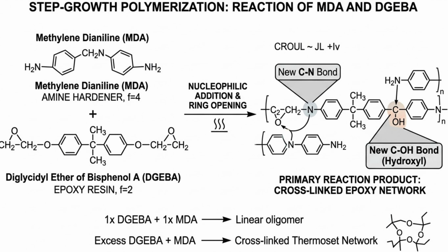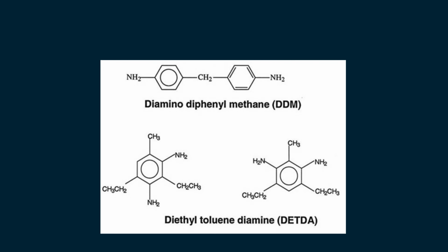Epoxy mixtures containing MDA generally have a longer pot life, about 20 hours, and cure more slowly. MDA epoxy systems also undergo B-staging, allowing them to be processed into solid adhesive forms such as powders or sticks. MDA tends to cause less staining during processing and is often preferred because of its lower cost. However, MPDA generally provides superior thermal and chemical resistance under equivalent curing conditions.